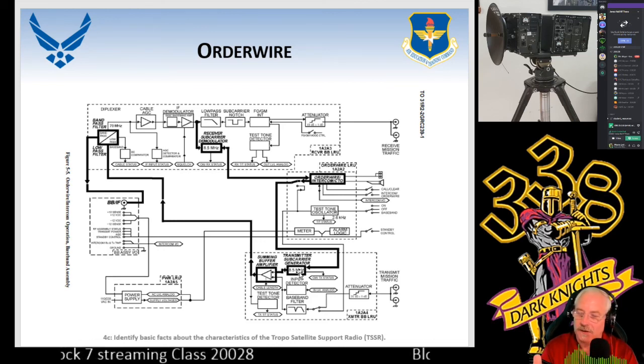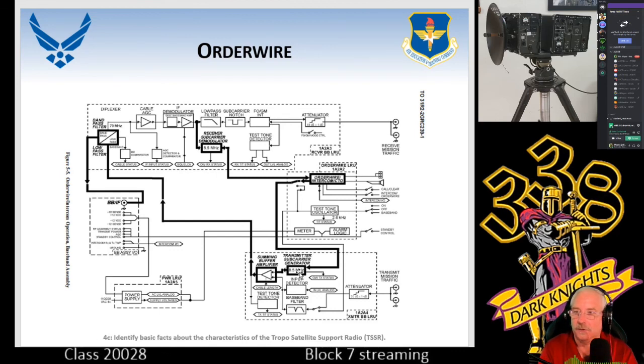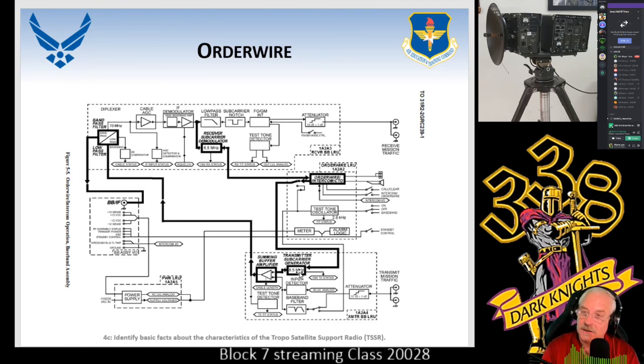If you take a look at this logically, the 8.5 megahertz should not interfere with your baseband, because I think the max on your baseband is 6.144 megabits per second. The 6.144 is not high enough to create problems for the 8.5 megahertz. So theoretically, you have an FM signal and a digital signal being modulated in the RF assembly.